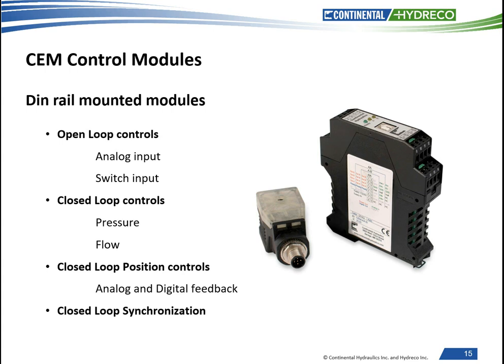The CEM PA card is for pressure or velocity control type applications. It is a closed loop card. It has an analog input resolution of about 0.006% on both the command and the feedback. Again, the communication is done through the USB Type B connection. There are some added features. Improved integrator control function parameters allow for tuning of a high loop gain application, and allow for less overshoot and stability near the 0 error set point.